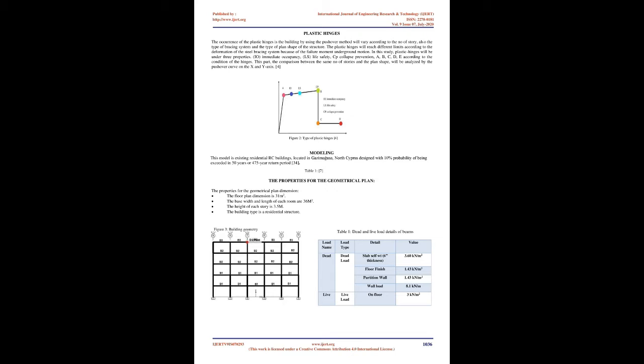The pushover analysis method. This method applies direct lateral loads on the frame, starting from 0 to a value corresponding to an exact displacement level, and determines the possible weak members and the failure members of the structure. The performance of the building is evaluated by using hinge positions at the target displacement, or the performance point, corresponding to an exact earthquake level. The acceptable performance is when the demand is less than the capacity at all the hinge positions, as the loading and assessment procedures are only virtually correct concerning the real earthquake hazards.